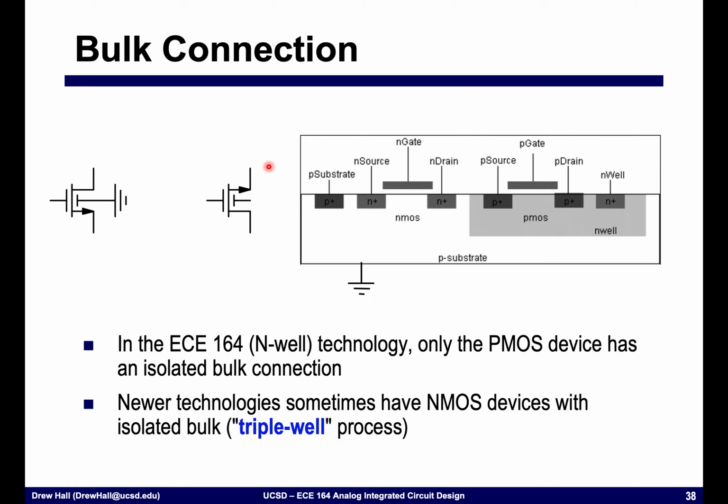There are some technologies that allow you to do the same kind of thing as we did for a PMOS, but for an NMOS. Instead of one well, we now have a second well where we have to put this into a P well and then an N well, in order to get back to having a P-type substrate. And so that's what's known as a triple well technology. Here you would say you have 2 wells, that adds the 3rd well.